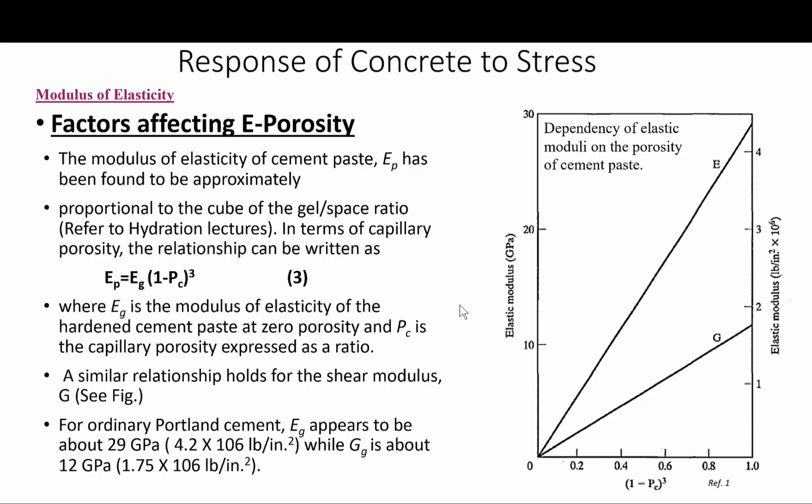One apparent inconsistency in the strength-modulus relationship is the moisture dependency of the two properties. The strength of saturated concrete is lower than that of dry concrete, while for the elastic modulus, the reverse is true. Let's keep that in mind.